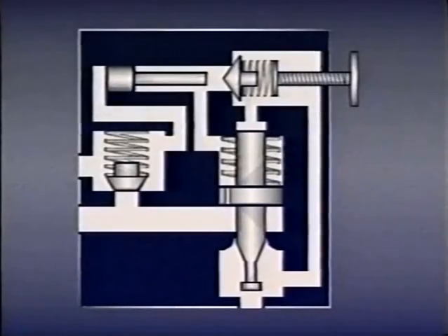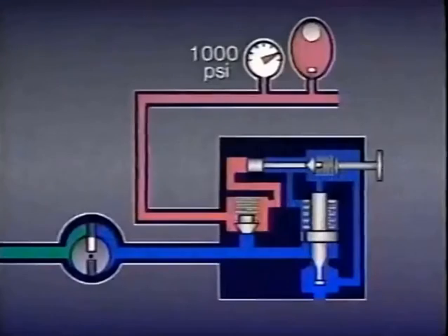One common way of unloading is with a differential unloading relief valve. This valve, specifically designed for use with accumulators, will automatically divert flow to the accumulator whenever it requires charging, but will unload the pump to tank after the accumulator is charged.